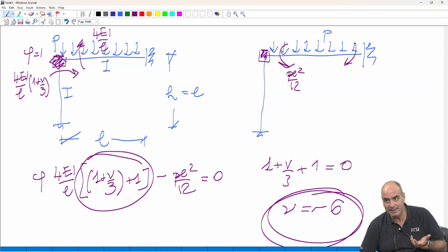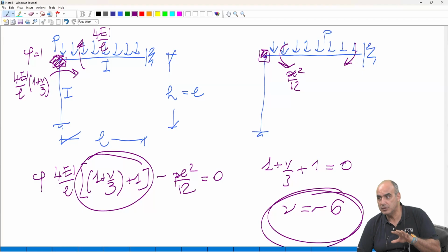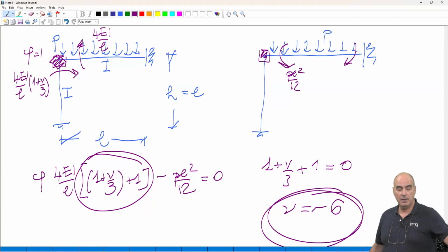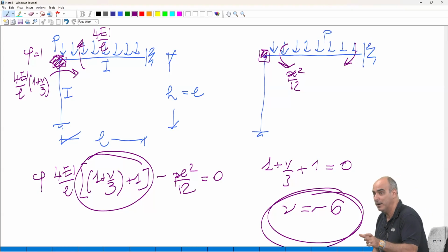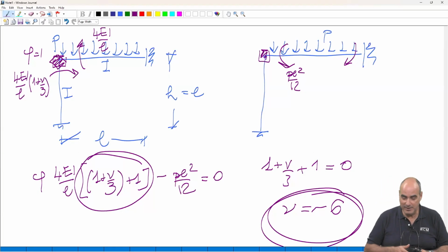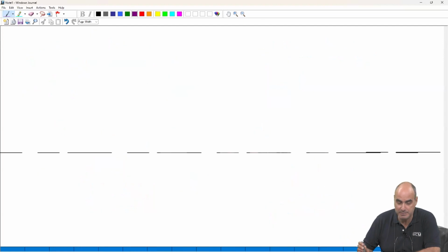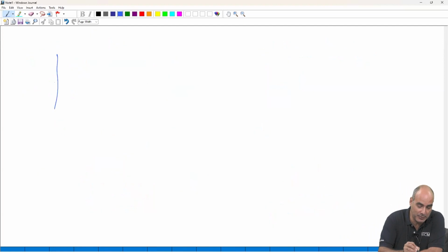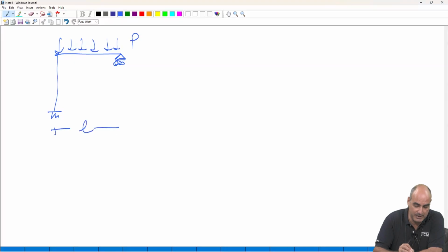So this is to show that if you try to apply the linearized theory to non-sway structures, you can get a strongly wrong estimate. You may say, well, I realize this, but sometimes you can get a number which is still in the range of admissibility, but which is wrong. And you don't realize that you are in the wrong regime. But since we must prove that the statement can be false, let's now try to say, okay, that same structure or a similar one